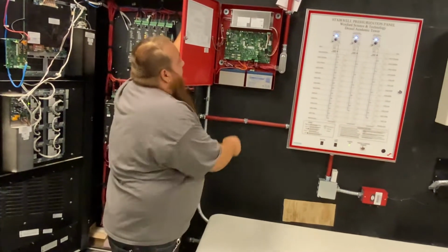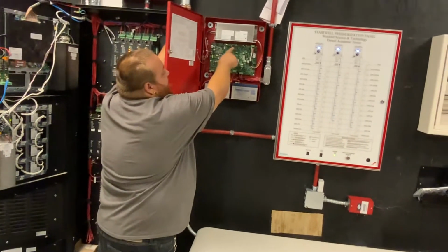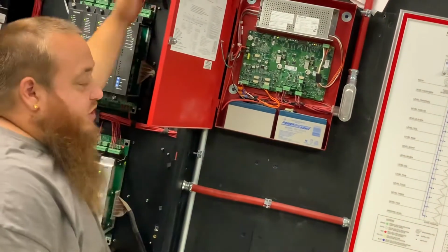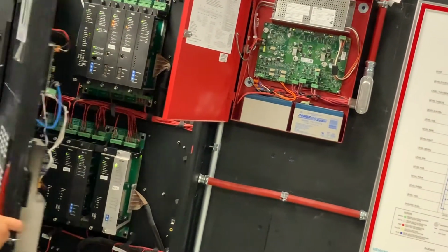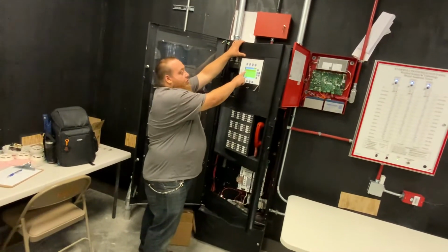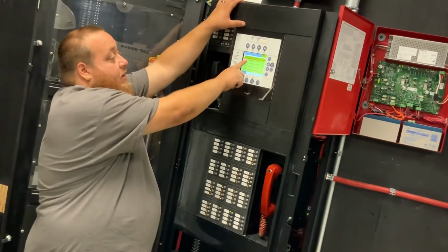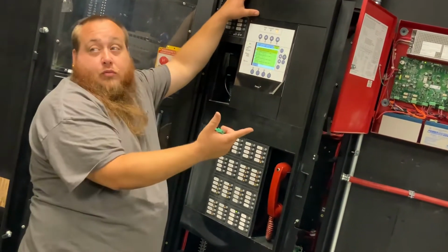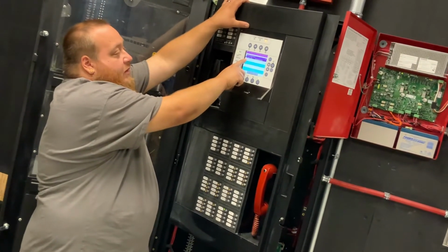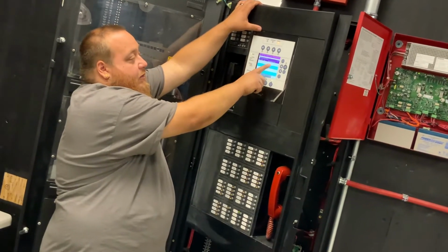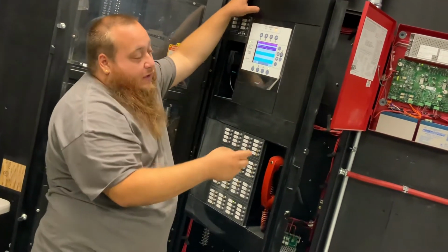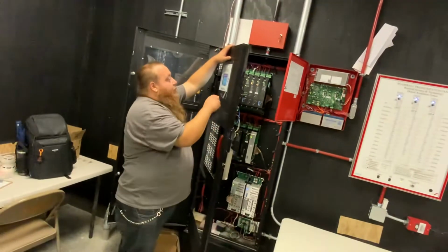It'll display. You notice now you have a flashing light. That means you have an open on circuit 4. Since there's a change of state, the system's going to know about it. You acknowledge it and keep it quiet. Since that pad's in trouble, you'll notice that it's on loop 1, device 83, pad 4 trouble, first floor electrical room 1-2. You hit more info, it'll tell you what device type it is, its number, what time it came in, and a quick description of what it is. And it'll say trouble caused an input, meaning that now that device is in trouble, it's inputting to let you know that something's wrong.